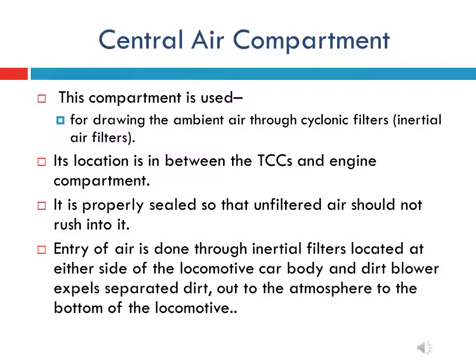Central air compartment. The central or centralized air compartment is a closed space located in between the TCC and engine compartment. On the left side and right side of this compartment, cyclonic filters are vertically mounted, through which ambient air is drawn into this compartment when the traction motor blower, main blower and turbo supercharger start working. To enter this compartment, a door is provided, which is to be properly sealed when the engine is running so that unfiltered air should not rush into it.